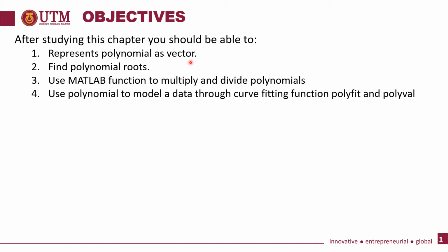Alright? So the second objective for today's lesson is to find polynomial roots. In MATLAB, you can use the roots function to find the polynomial roots. The third objective is that you will be able to use MATLAB functions to multiply and divide polynomials. And the fourth objective is that you will use polynomials to model data through the curve-fitting functions polyfit and polyval.